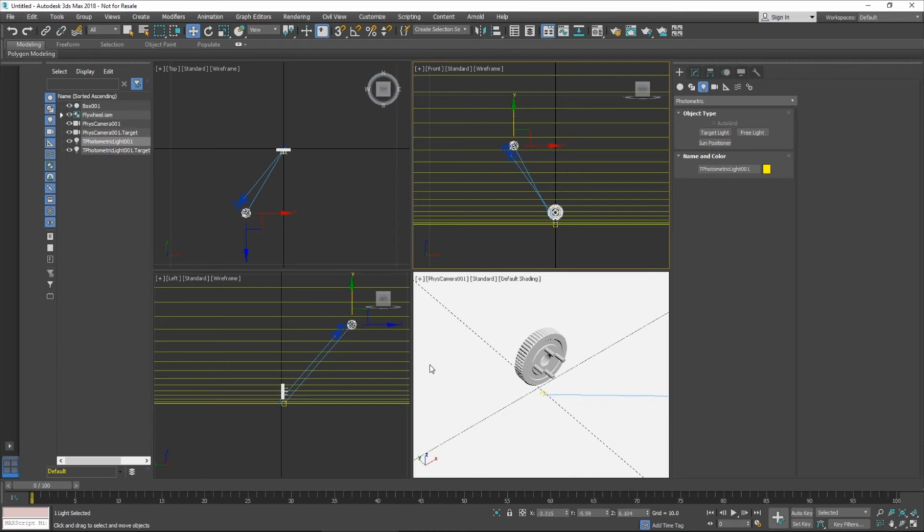And that's all we need. Basically, we need the Virtual Studio box, the cameras, and then the lights, and then we're all good to go. Those are the 3 basic things you're going to need in order to render quickly and effectively. And the great thing is that now that we have made it once, you can actually export it out as a 3ds Max file to be used later. And you have kind of like a template, quote unquote.